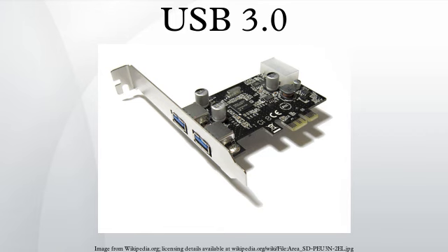Pinouts: the connector has the same physical configuration as its predecessor but with 5 more pins. The VBUS, D-, D+, and GND pins are required for USB 2.0 communication. The additional USB 3.0 pins are 2 differential pairs and 1 ground. The 2 additional differential pairs are for SuperSpeed data transfer. They are used for dual simplex SuperSpeed signaling. The GND drain pin is for drain wire termination and to control EMI and maintain signal integrity.